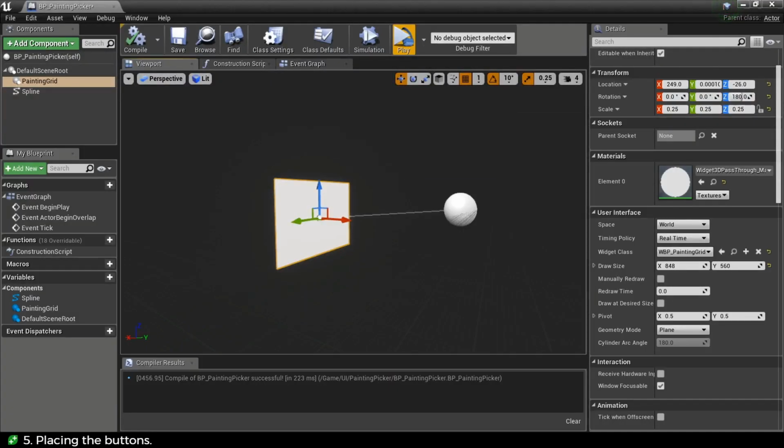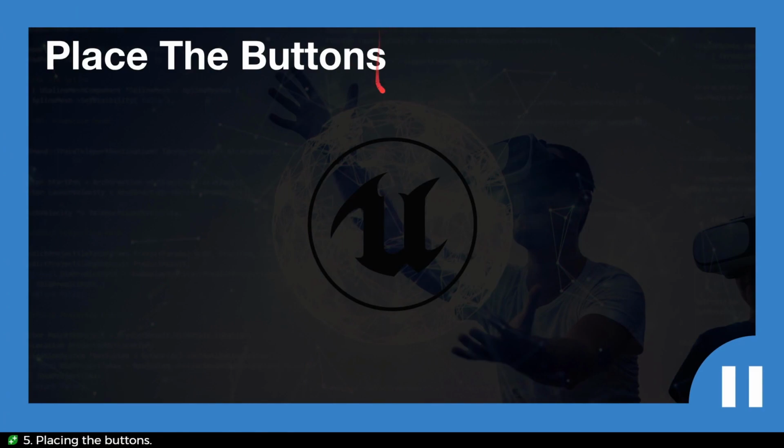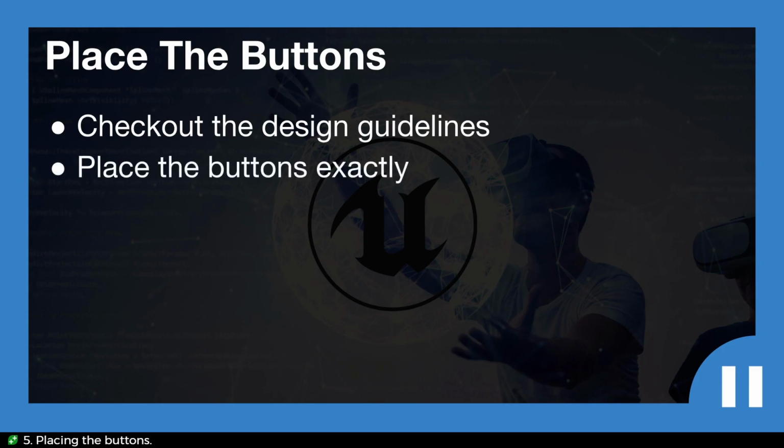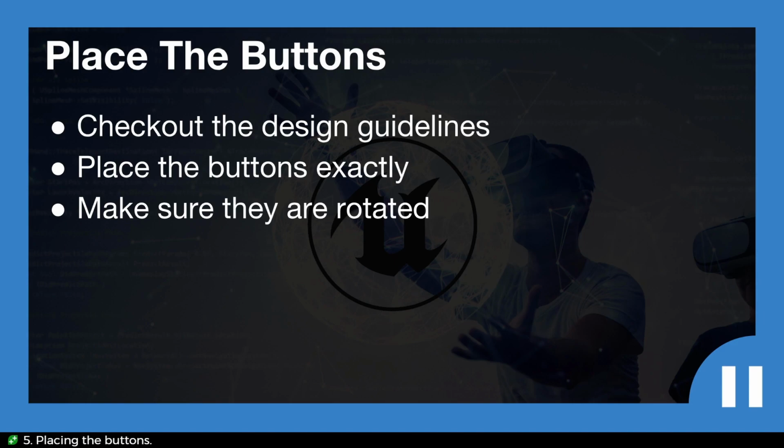So the buttons are now going to be your challenge to place. So place the buttons. Check out the design guidelines for how far and how far down they should be. Place the buttons exactly, make sure they are rotated, because unlike the back pane, we are going to rotate the buttons. Have a look at the side view in the design guidelines to see. Make this the right scale. So have a look at your buttons in your UI design. How big are they? Basically just draw a box around them, and try and make them the right size and scale, and think about the dims, so how close they are to your eyes, so that is all correct. Pause the video and have a go.